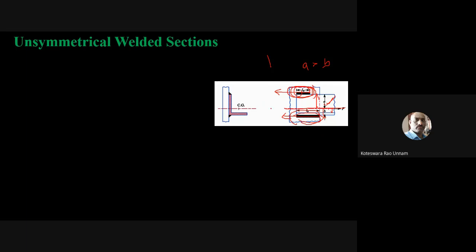So therefore you don't have any net bending moment on the joint. So therefore the joint is subjected to only the tensile load, or that means only tensile stress. There won't be any bending stress because the bending moment is zero.